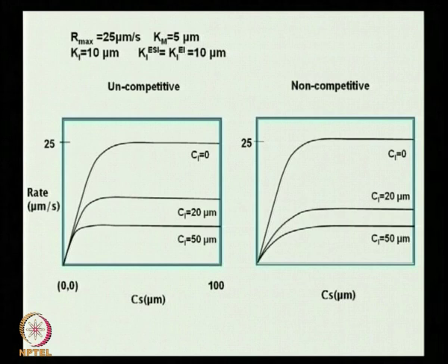By reducing the RPM. No, RPM, no, let us not get into mass transfer resistance at this point. Okay, the answer is this, that instead of using one large reactor, replace it by several reactors. So, if you have a reactor of say 10 hours residence time, replace it by 3 reactors or 4 reactors of 2.5 hours each. So, the total residence time is still the same, okay. And if you keep the total amount of the flow rate as the same, then you essentially divide up. So, a 10 liter reactor you divide up into 4 2.5 liter reactors, right.